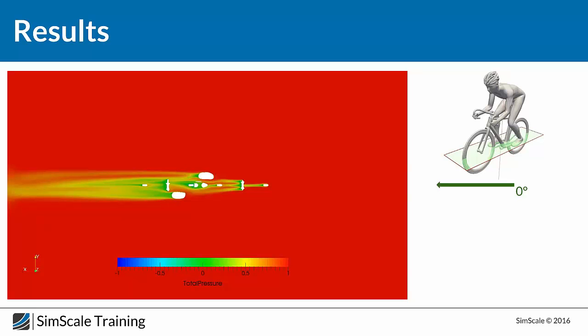Let's jump to the next one, and here it's remarkable, and it's clear that with the large tires the wake is really small, and I'm going to tell you why. The idea is, for the thin tire, the flow moving beside the tire just over here will not have enough space to develop the boundary layer. So it's still a laminar boundary layer, and that's why this flow cannot stay attached over this curvature in the back of the tire.